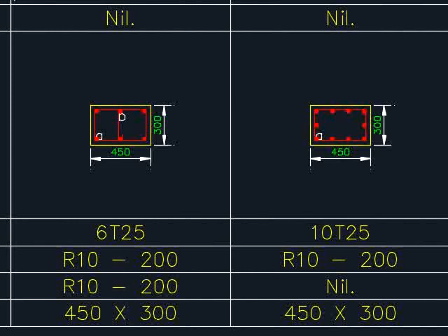Sometimes the amount of reinforcement bar increases significantly not necessarily due to the axial load. You know that concrete is very good in compression, which can be a part of the resistance to the compression load. It is very often that because of the bending moment as well as the slenderness of the column, the amount of reinforcement bar increases significantly.